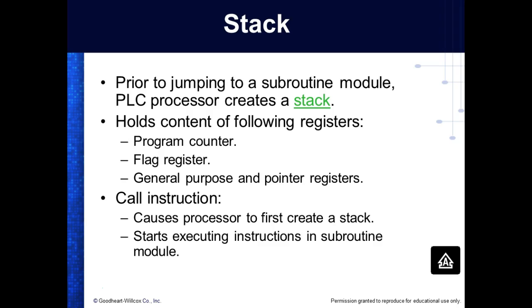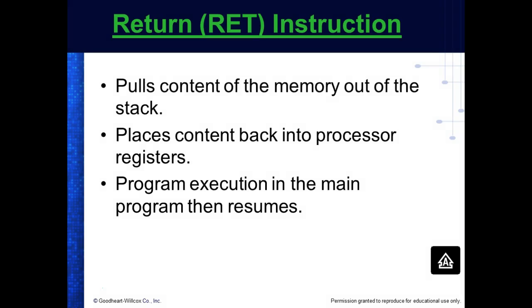This causes the information to be pushed on the stack: everything that was going on with the instruction, the program counter, the flag register. Because it might have to use these same registers inside the subroutine, right? Does that make sense? Then it pulls the contents of the memory out of the stack when it hits the return instruction, places the contents back into the processor registers, and then starts executing the main program.